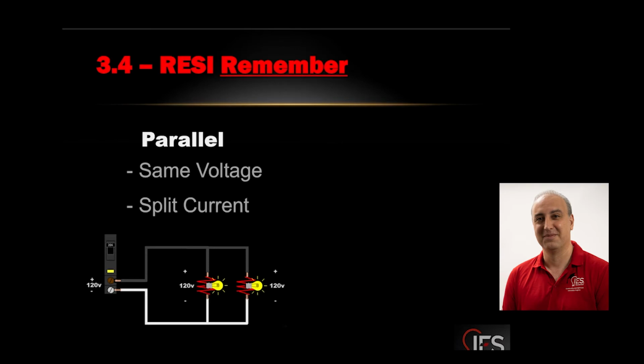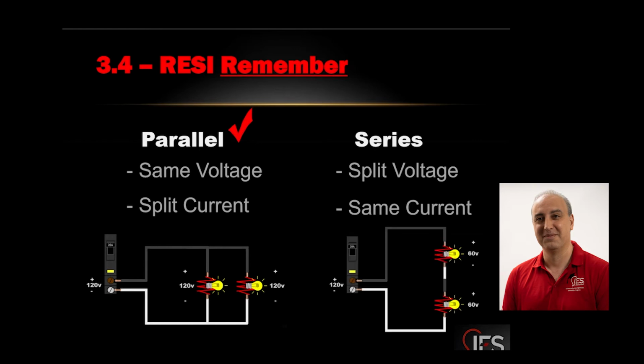So, take-home message from this slide is that our residential installations should be parallel. We have a system that's designed to work on 120/240 volts. We want to keep it always the same, so we hook up everything in parallel. And in parallel circuits, voltage is kept the same, but the current splits, or usage of current changes. In series is the opposite. The current stays the same as it goes through the same size equipment, but the voltage changes, and that's a no-no for us. We have system design, so we don't want anything to get different.